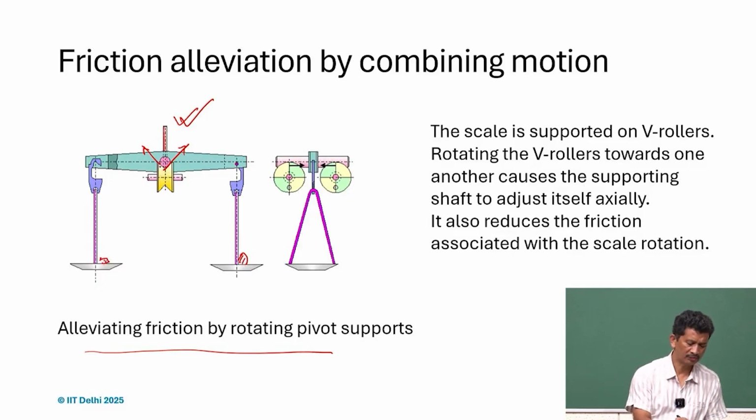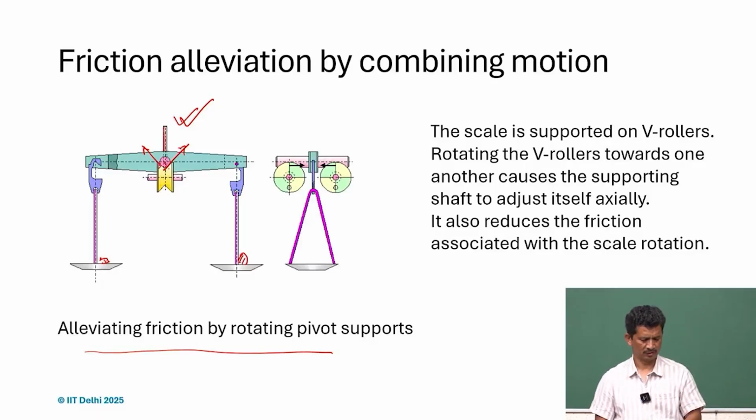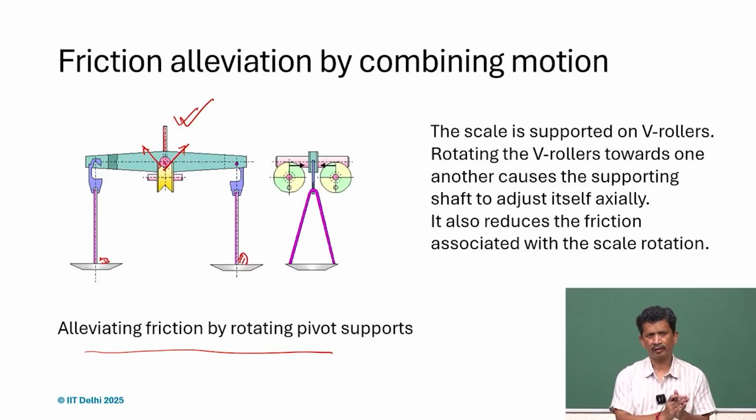It always gets limited by the accuracy here, because there will always be some friction there, and it will add to that value. So that is the uncertainty we'll have. It can get locked anywhere, just like the previous case where we have the body and the spring attached, and it's a zero, but it's not zero because it can always get stuck at a certain location if it's within that virtual play. Similarly, here also it can get stuck, and that amounts to the error in the measurement.